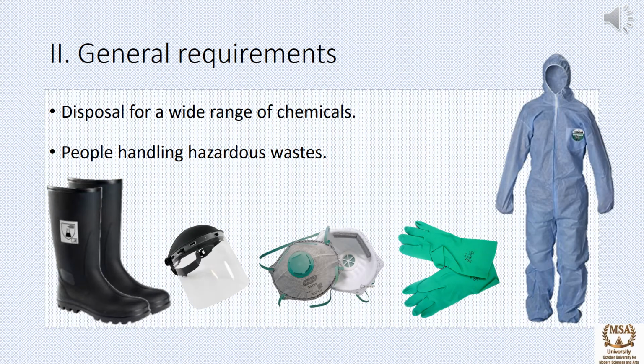General requirements. Disposal is necessary for a wide range of chemicals which possess an inherent health risk and environmental hazards. However, the quantity or the method of treatment might be. People handling hazardous wastes from segregation to disposal should be supplied with suitable protective gear, including face masks, boots, and hand gloves.